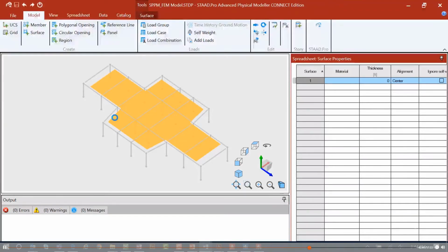But basically, if you want a specific point within your surface area to be considered a node, all you have to do is basically create a node within that level. And that's the same exact thing as creating a density point. So if you want, for whatever reason, a specific point to be considered and to attach your finite element mesh, you're just going to create a node within that area, which you can do through the node spreadsheet in the data area.